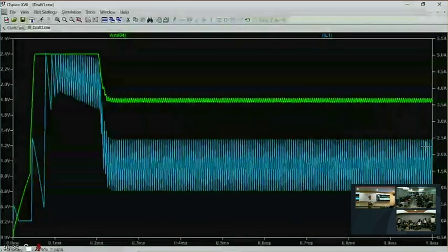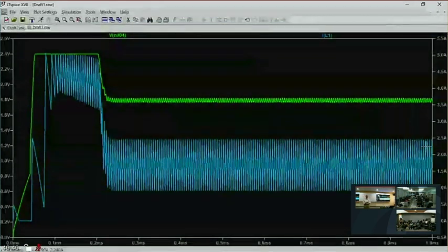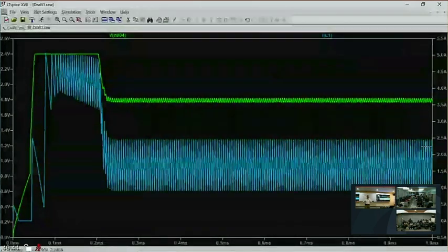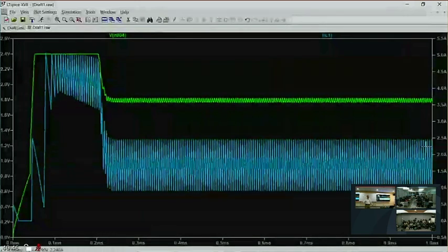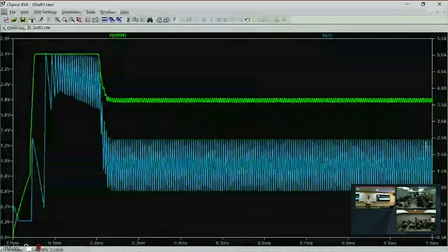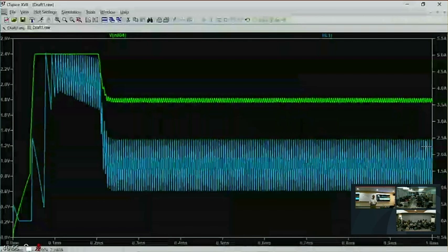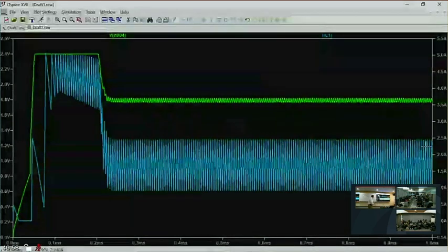That's great. But if you have a sine wave and modulate it FM with a sine wave, the envelope of sidebands follows these Bessel functions, and they go on forever. But it's noisy, so you're not modulating it with a single frequency, you're actually modulating it with many frequencies. You simply have sidebands